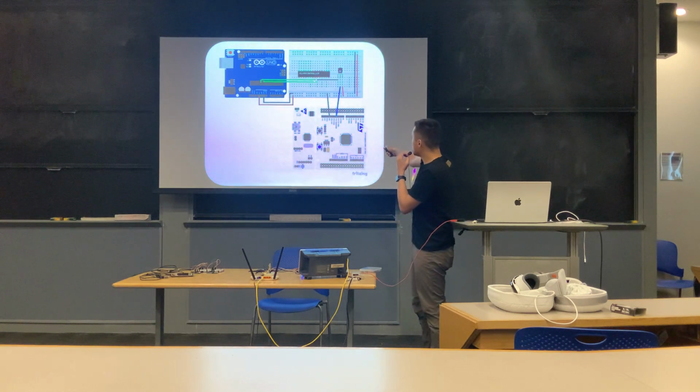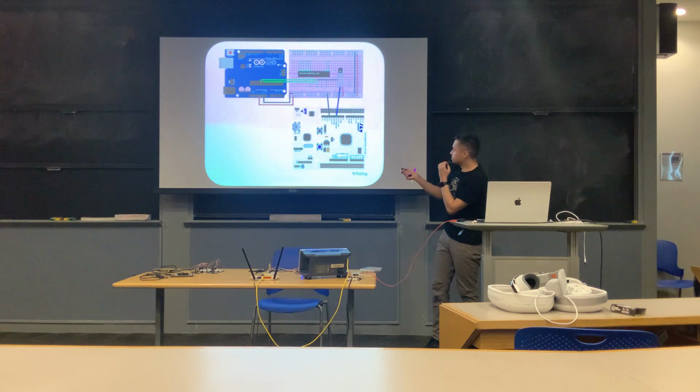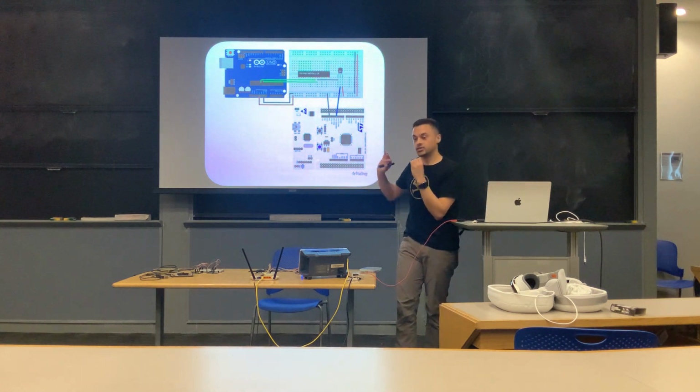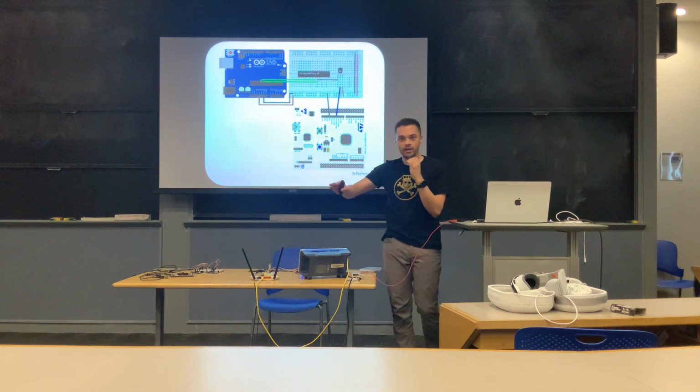And then what we have is these two pins that go to the oscillator, which is on the board, and the second pin to the oscillator is attached to this transistor. This transistor is driven by an STM32, which is a very, very fast microcontroller. It's actually so fast that we can inject these tiny spikes way faster than the Arduino is able to handle.